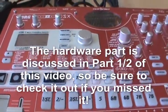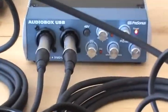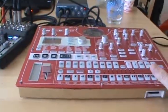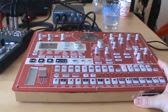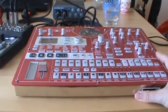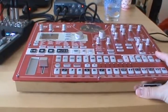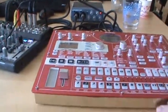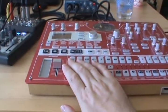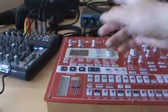If it's just MIDI data, then you need one of these. So you're ready to go. If your synthesizer has a built-in audio interface and your USB port serves also as an audio port, then you don't need an audio interface. Just put the USB cable into your synthesizer and then into the laptop.